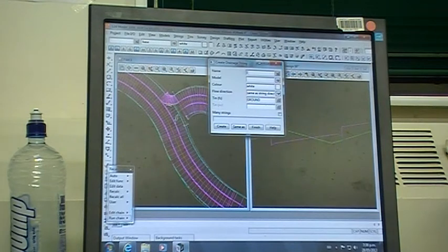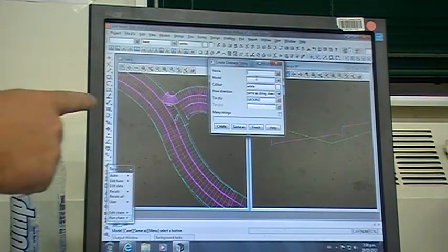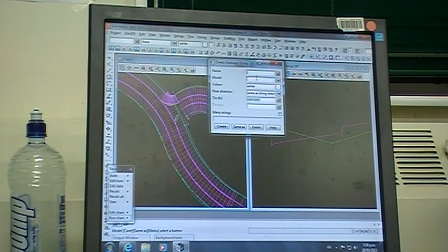So I'm going to do a stormwater line 1. Like everything else, I keep my naming convention simple, so the model that I'm going to put all my stormwater lines into is called stormwater lines. We end up running functions on these. You have to put everything into the same model, in the same way that our centre lines work. Well, you don't have to, but the functions won't run properly otherwise.